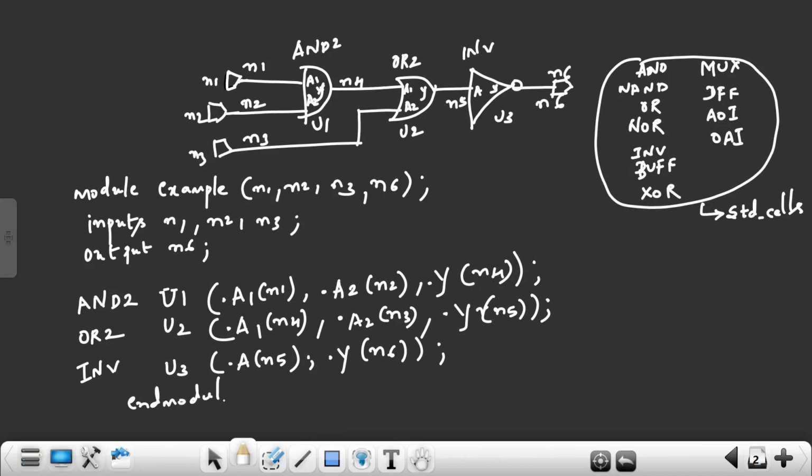So in this netlist, I have only gates and gate information. I don't have any assign statements, if statements or case statements as we have in RTL. My netlist should have only gates and their connections. In the netlist I have written, is there a connection from one gate to another?